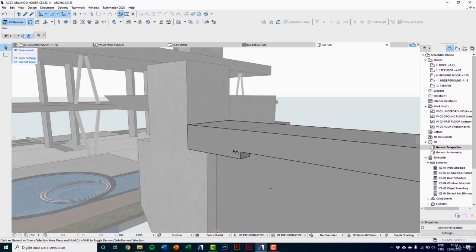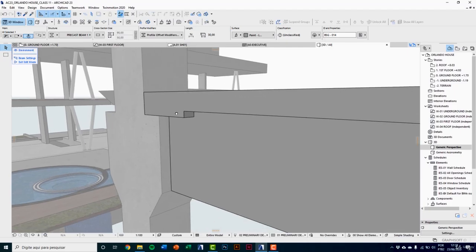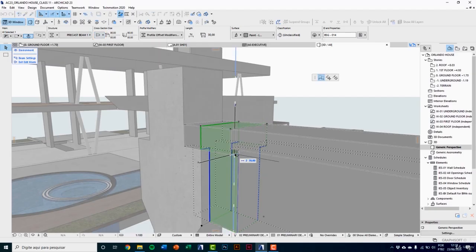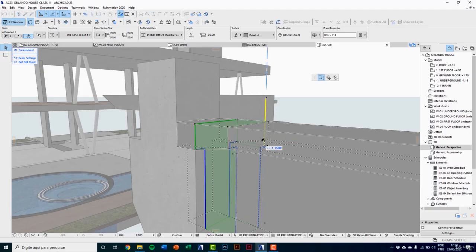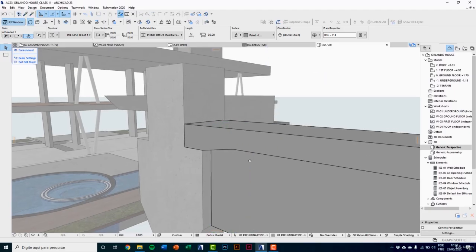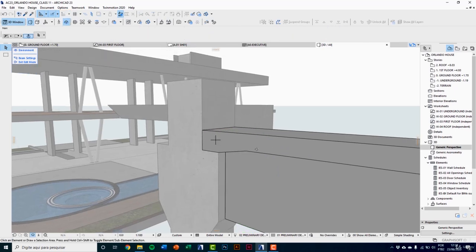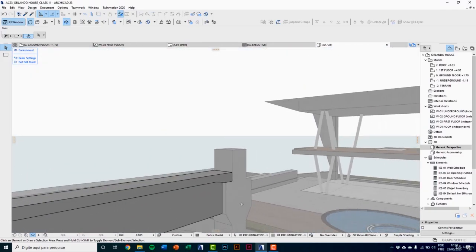And now, selecting here this cross section, I can do the same, but now I'll change here to tapered size. And clicking on blue line, you can elevate this element, making a slope on bin. I do the same on the other side. And so you can see that it is a versatile element, a great enhancement on Archicad 23 to do structures of variable sections.